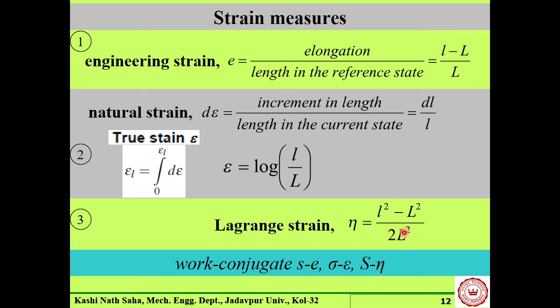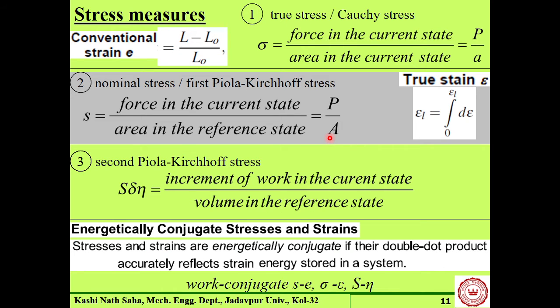That is what we measured, the Green Lagrange strain. That was the nonlinear relationship between strain and displacement. But the engineering strain and displacement relationship was linear. We omitted some terms of this Green Lagrange strain and obtained a linear relationship. You remember that. So, these are different types of stress and strain measures.